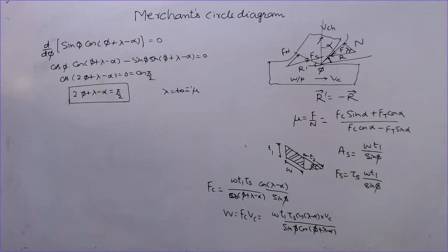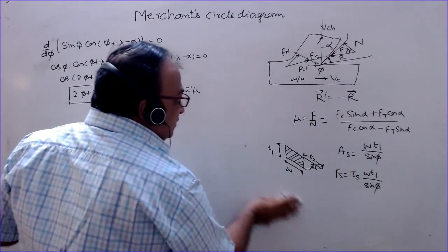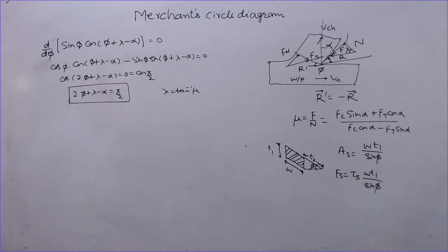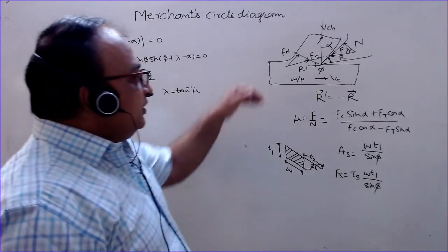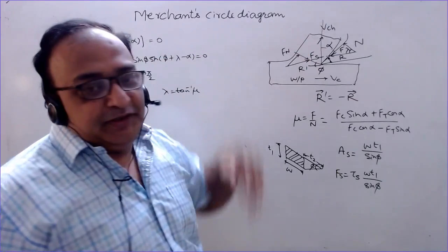So as a result of this, Merchant investigated and found another relation by considering the normal stress during the cutting operation also. Let us discuss Merchant's modified relationship. As you can see here, the shear force Fs is acting along the shear plane.